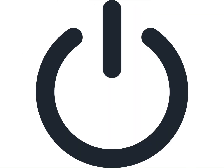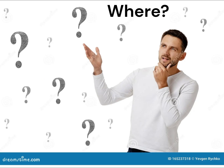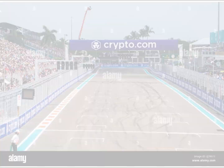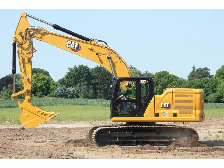Next, I'm going to talk about the safety standards according to IEEE STD 1547. First, instantaneous power must be monitored at the point of common coupling. In our case, the point of common coupling is the point where the solar panels connect to the grid or a network. The monitoring must be done to prevent reverse power flow, which can damage the equipment.